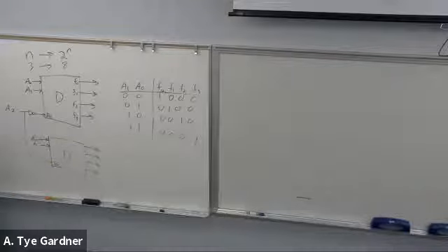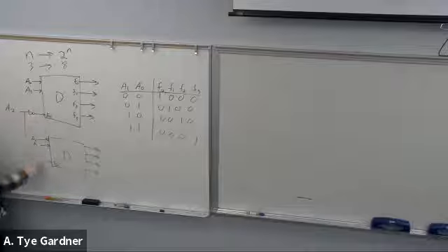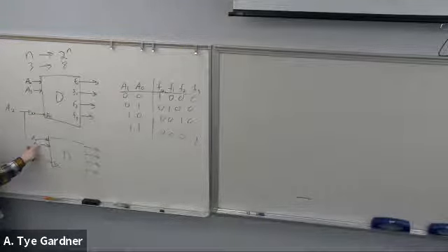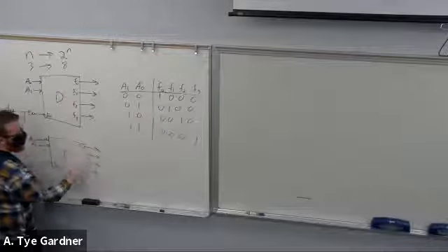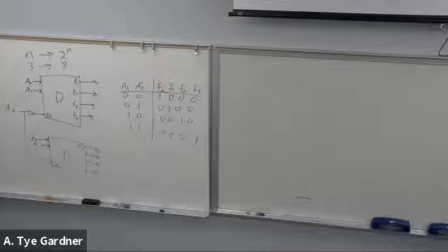Conversely, if I get 1, 0, 0, 1 means this enable is off and this enable is on, and A0 and A1 are 0, 0, and I get what I'll call F4, right? There we go. So now I have a 3 to 8 decoder that is using this idea of design reuse. I just used what I had, added literally one inverter.